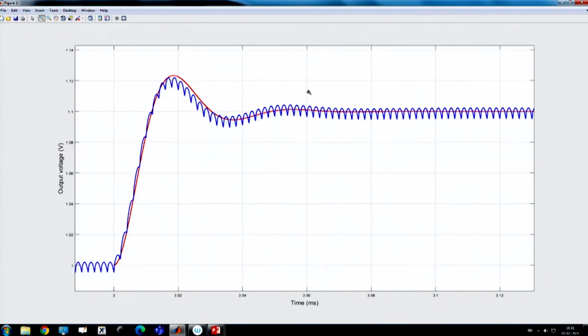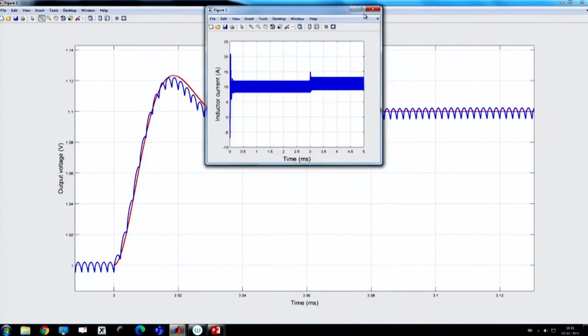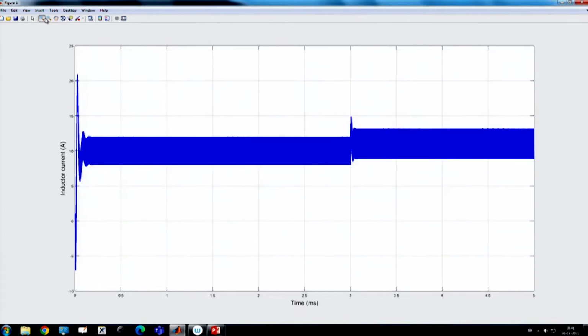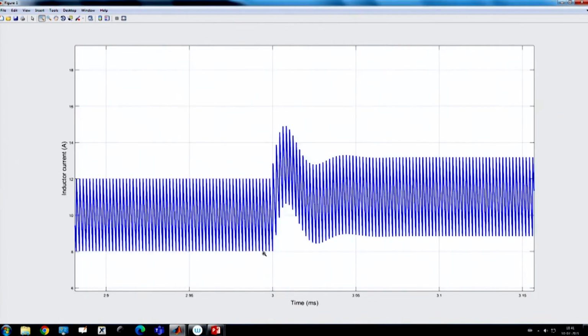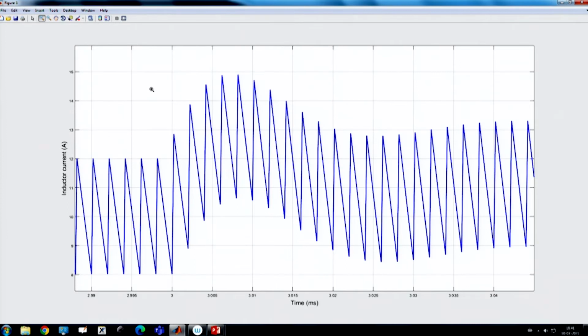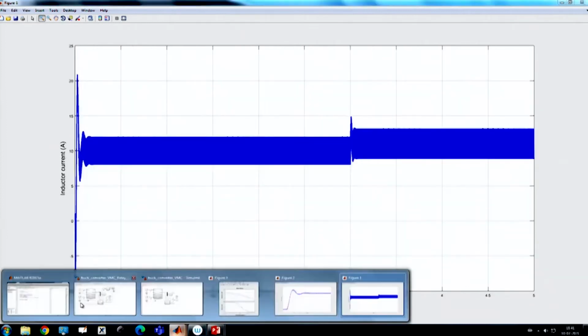So, in this case the validity is at least 1/20th of the switching frequency, because maybe the step size is large. It will be clear from the current waveform; the reason is nothing but that the duty ratio perturbation is somewhat larger. So, they are not exactly matching, but closely matching.